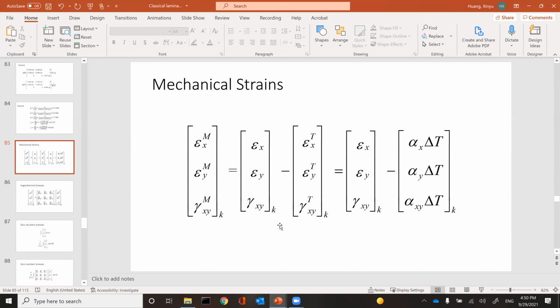If two layers are fighting, the stress of you pulling on me and me pulling on you is always equal, right? It doesn't matter how many layers. Once you slap them together, they'll find a balance. We can figure out what that stress is by doing this kind of thermal analysis. So this is a fundamental equation to enable that analysis.